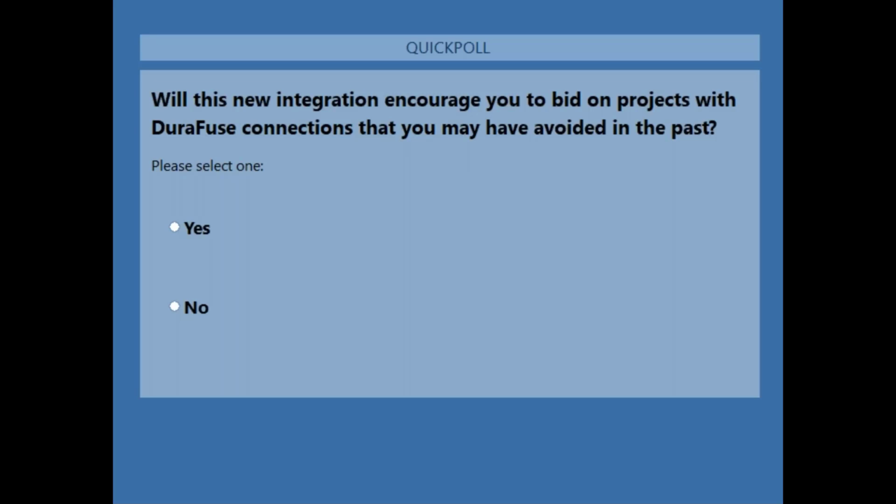Right. Next question. Is the bottom fuse plate a steel plate? Yeah, that's a great question. So all of the material in the connection is standard steel plate, A572 grade 50, and that's for the fuse plate and for all of the other plates in the connection.